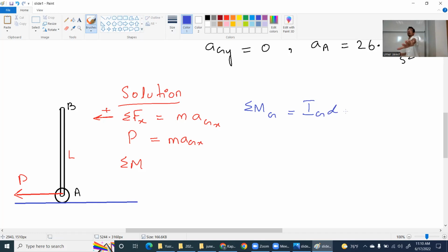Okay, we are all on the same page that when it comes to center of mass, it's I alpha. Don't worry whether this point is going to the right or the left or it's moving or not. We have no issues in this IG alpha. I have told you quite a few times. Now let's tackle this IG as 1 over 12 ml square, theta double dot. Okay, what about summation mg?